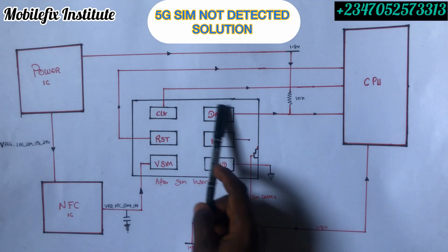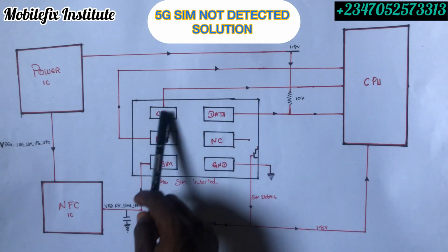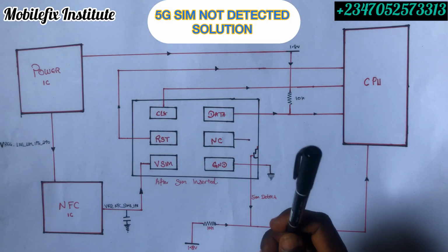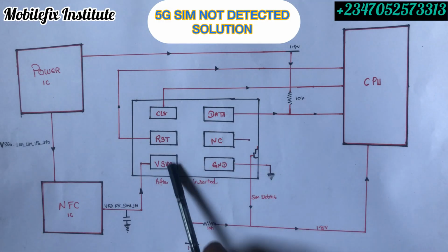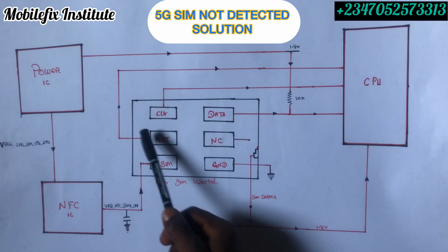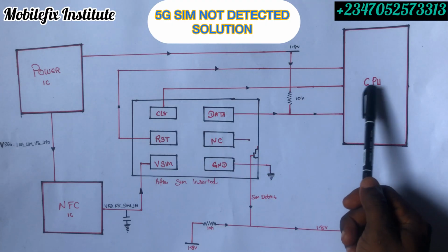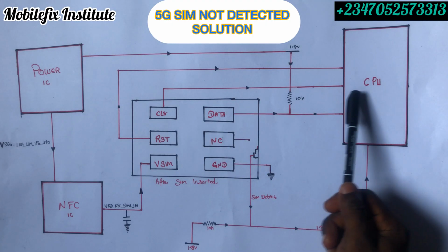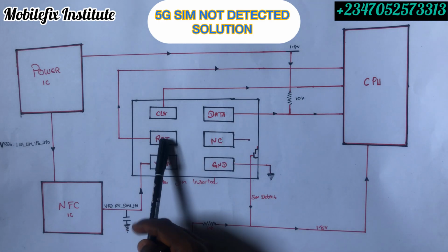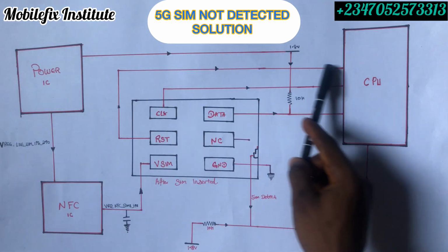Now, after examining this SIM port, you have to take diode readings on these 6 pins. The first pin, which is our clock, will give you readings because it's connected to our CPU directly. Then our second pin is our reset pin, so it will give you readings.